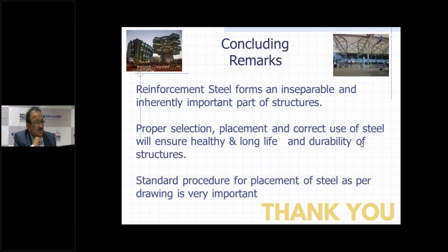And Mr. Damodar Sahu is asking, can we use PVC cover block? PVC and plastic both have an issue of bond with the concrete. I would prefer concrete blocks. Nirav Patel is asking, what is the diameter of the couplers, and will it affect the clear cover criteria? The coupler's body thickness is around 3 to 4 mm. To that extent, the cover will be reduced.